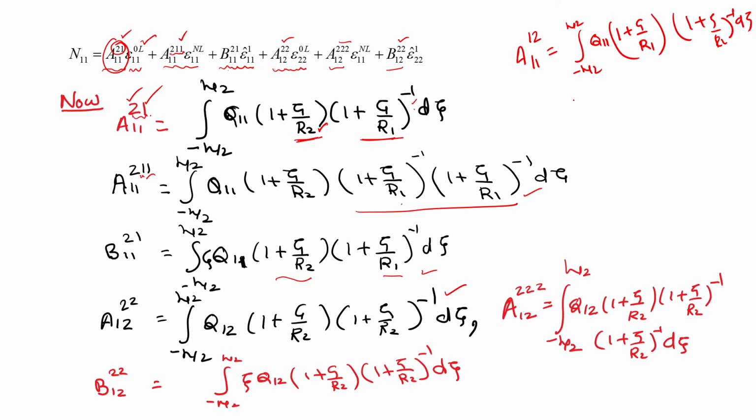In the case of a plate, A11 is sufficient because A11 in the case of a plate is just Q11 integrated over zeta. Here we do not need the second index because there are no such terms, but now we have these two terms. So, you will have the components of N22 and N12, N21. We may forget which comes where, which will be the inverse one, so this will help us to find the inverse term properly.